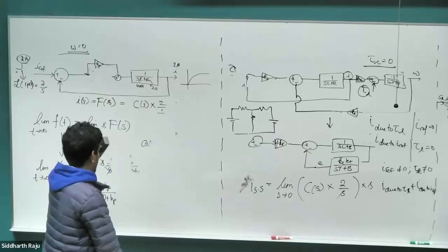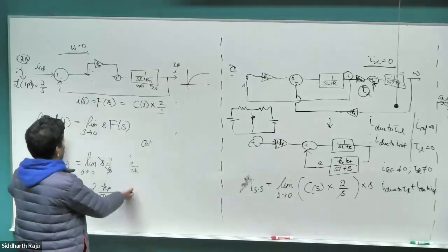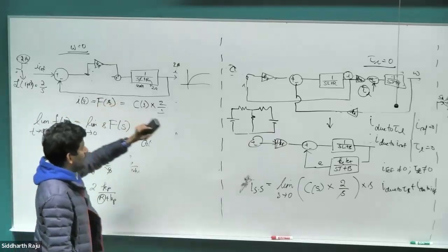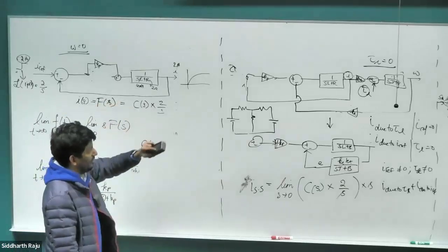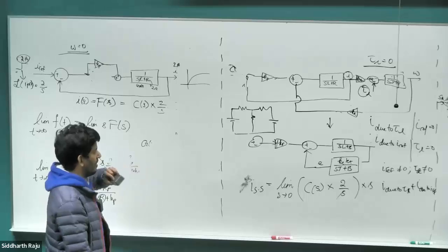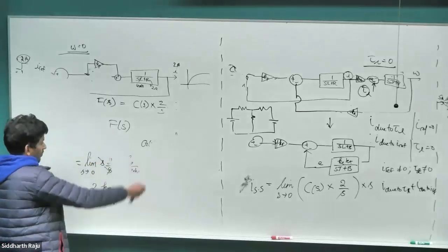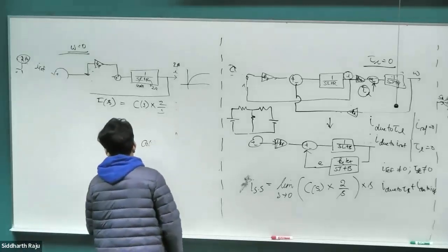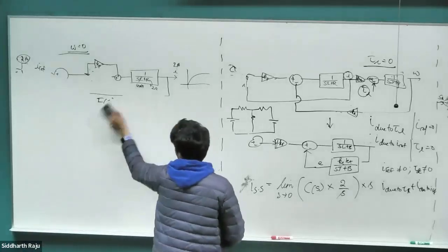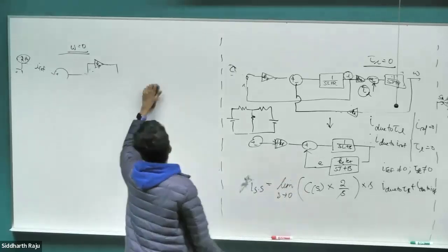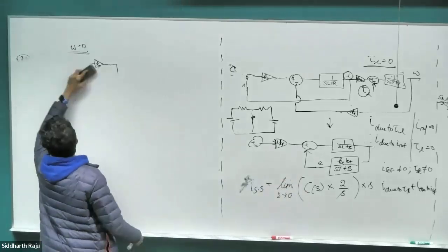If you look at your simulation and take out the KI value and you figure out the value from this method, it will still not be correct. If the load torque is 0, you'll get the correct answer, but once you put the load torque, the steady state current will change with just a pure proportional controller. So for that one, you need to do supervision and figure out the correct value. But if I ask you in the exam, definitely do the correct method, not the half answer work.